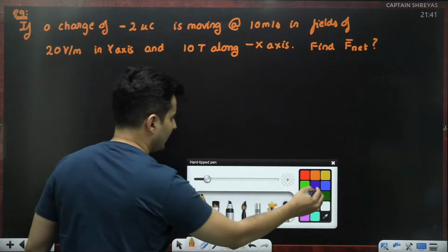Okay. I can see a beautiful right angle triangle getting formed where the hypotenuse is L, the base is L by 2. Can you see that beautiful triangle? The base is basically L by 2. The hypotenuse is L. What is this angle going to be? This angle is just going to be 30 degrees. So if this angle is 30 degrees, this angle is also 30 degrees. That means this angle over here is going to be 60 degrees because this total should be 90. If that is 60, that means this theta should be 30 degrees. Hence, I get that the deflection is 30 degrees. Done and dusted. So a complex problem was actually simple if you do it properly by geometry.